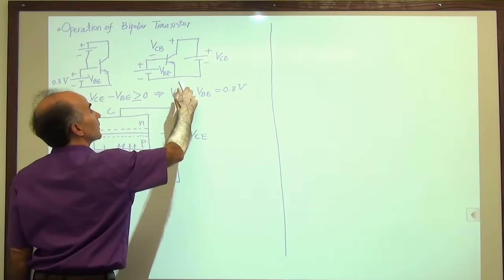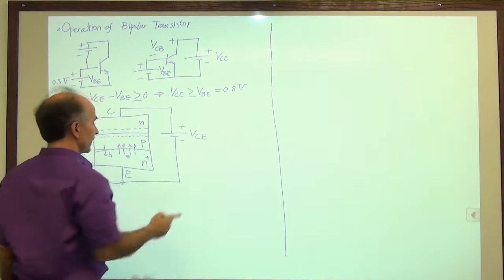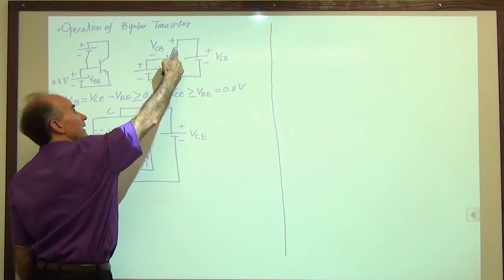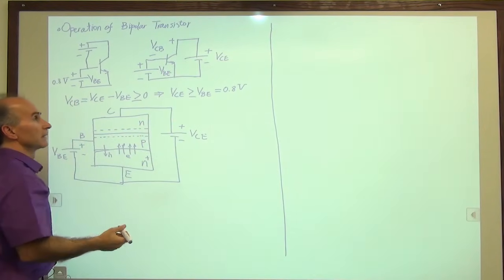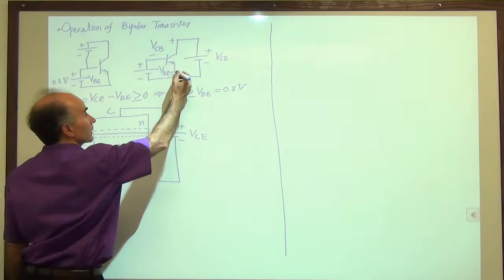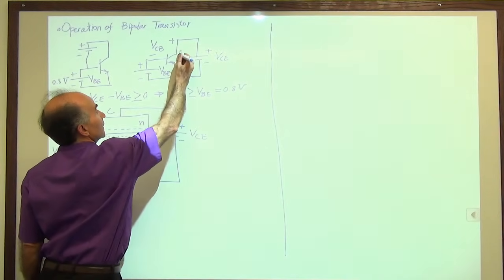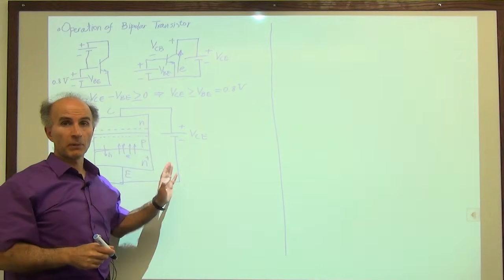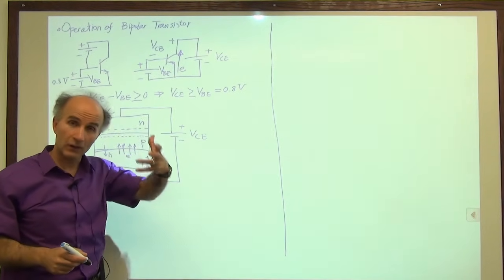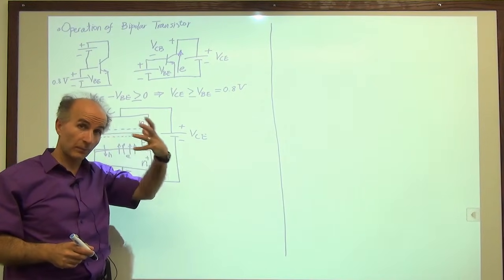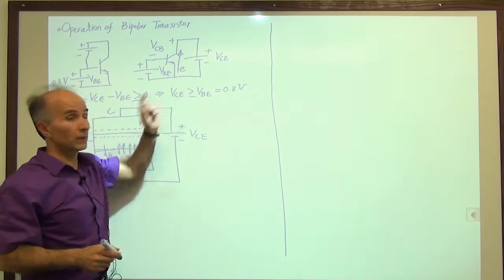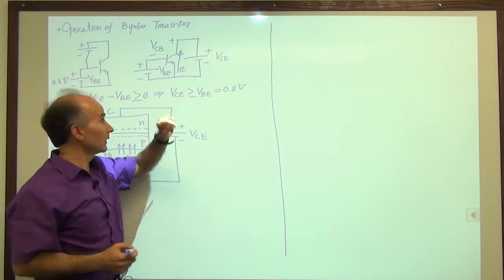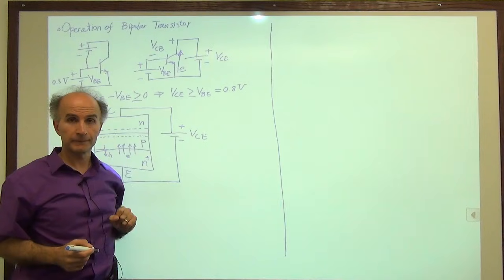All right, so we see that electrons are traveling this way and then end up in the collector and go that way. And that's what we get for these guys. So these are electrons going that way. If electrons go from bottom to top, the conventional current, which is associated with positive charge, is going from here to here. So equivalently, we can say the conventional current is flowing from collector to emitter.